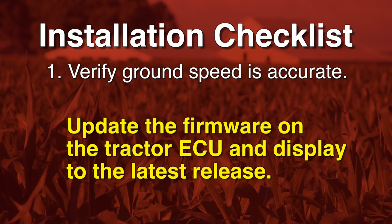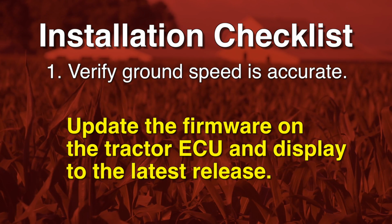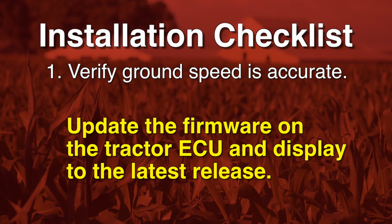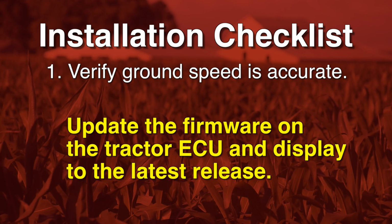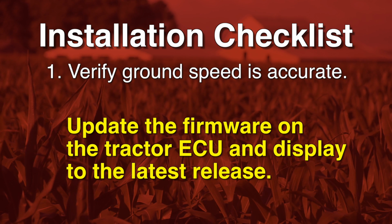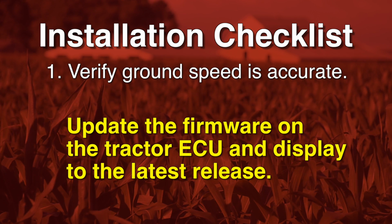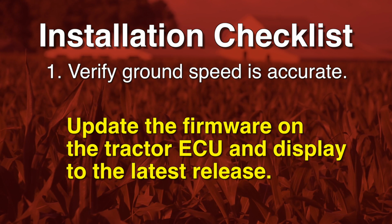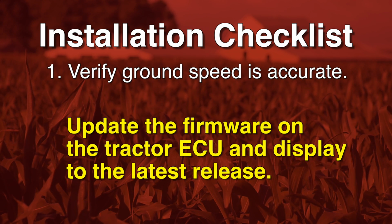If the firmware on the tractor ECU and the firmware on the display is not up to date, you may be getting an inaccurate speed reading. Once the ISOBUS system is installed, the tractor is now receiving speed from this source. Update the tractor ECU and the display firmware to the latest release to guarantee that your ISOBUS system is correctly communicating the tractor speed.